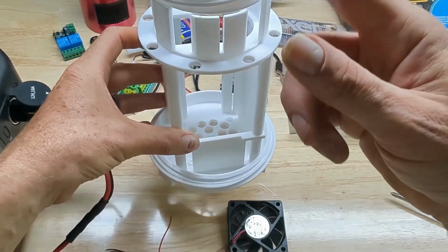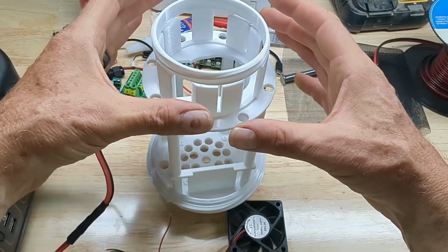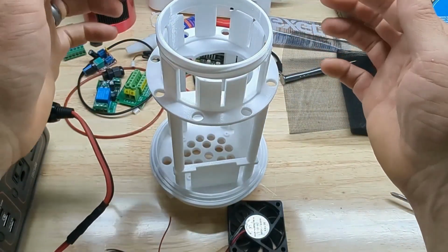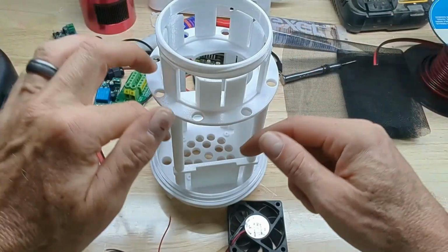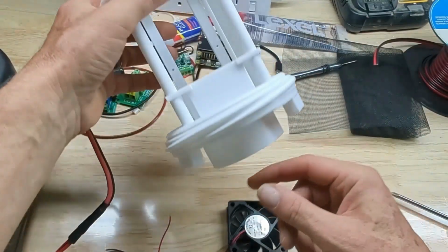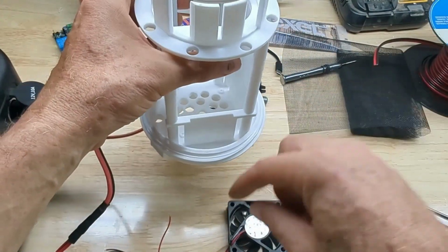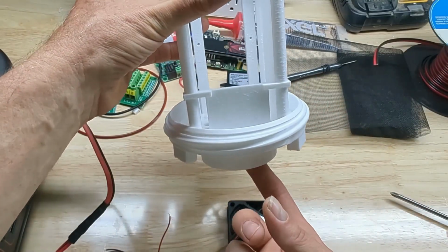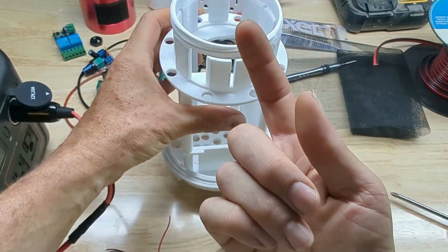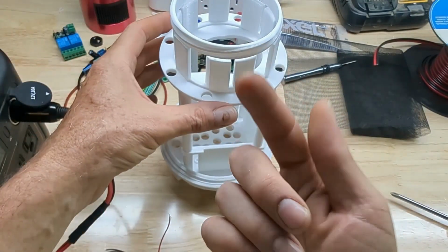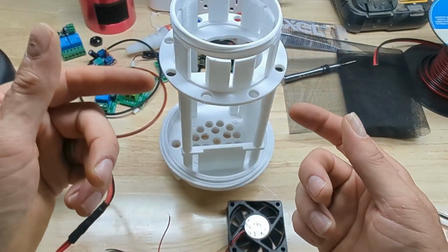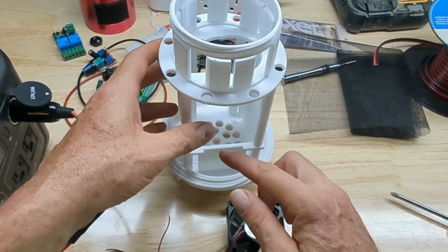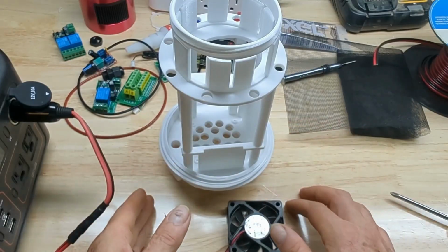My plan is to pull air from the top down. So when the tube is on here, the tube has those holes around the neck. It's going to draw air through that, down across all the components to keep everything cool, and exhaust it out the bottom. The reason I want it to exhaust out the bottom is I don't want air or dust to be taken from here and blown up into the dome area, because it would probably look like those confetti balls the kids used to roll around, where things are just popping up in the air. Don't want anything like that. So I'm just going to take the air from the sides and pull it down across the components to keep everything cool and exhaust out the bottom.